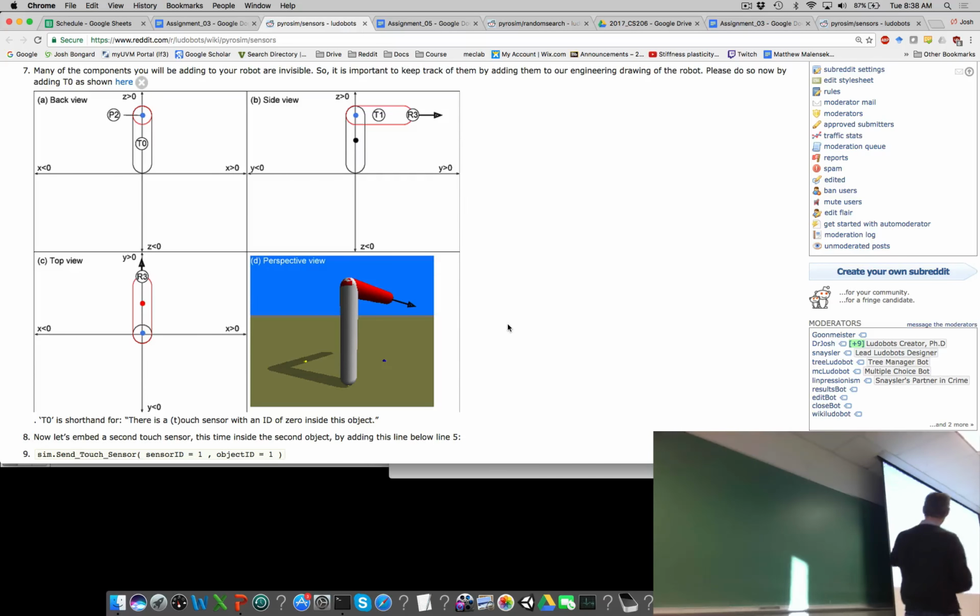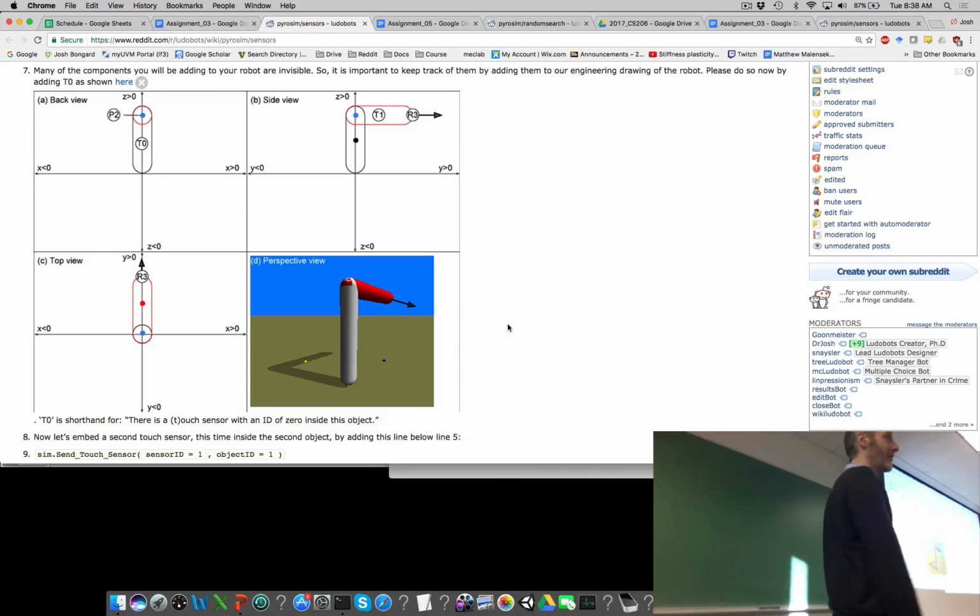And then finally, you're going to be adding a 4th sensor, the ray sensor. As the name implies, the ray sensor sends out a ray and reports the distance of that ray. If it's pointing off into the distance, that sensor reports its maximum value, which is 10 units of distance. As the red cylinder starts to rotate down towards the ground, that ray will collide with the ground, and the value reported by that sensor will shrink.